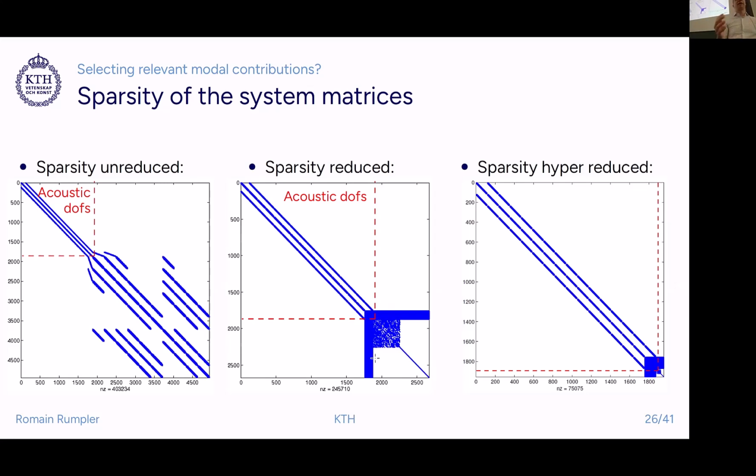which is a bit, there's no proof in there. You're just checking a posteriori, but essentially it tells you that the subspace spanned by the eigenvalue problem based on this low frequency stiffness matrix and mass matrix may be decently aligned with the one that would have been generated if we had taken the other matrices that we have in the initial problem and have neglected for the eigenvalue problem.